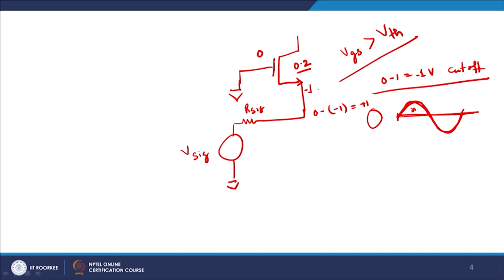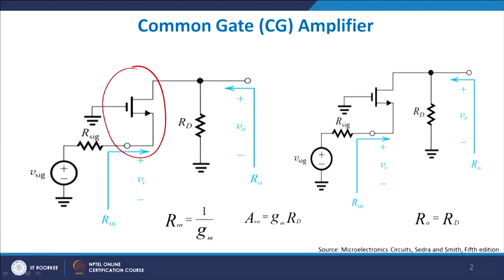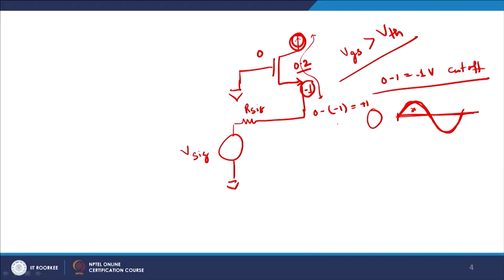Secondly, why there is no phase difference between drain and source? Because if you look very carefully, whatever potential you are giving here, the same potential will appear at this edge, right, because the same current has to flow between these 2 points, and therefore it is not out of phase, it is perfectly in phase. Therefore, common gate is basically a non-inverting amplifier, and the second thing is its Z in is very low and Z out is relatively high. Okay.